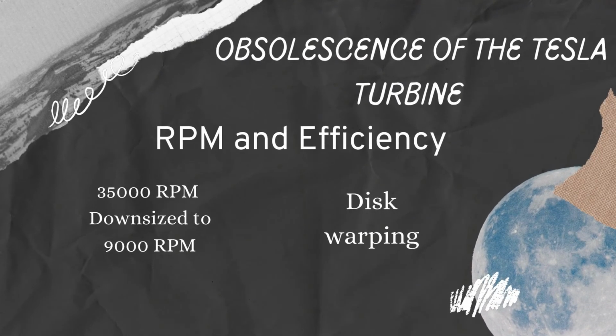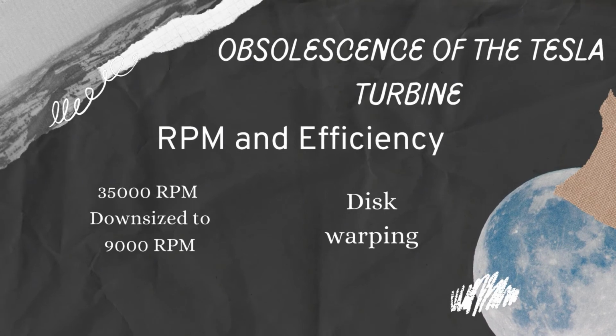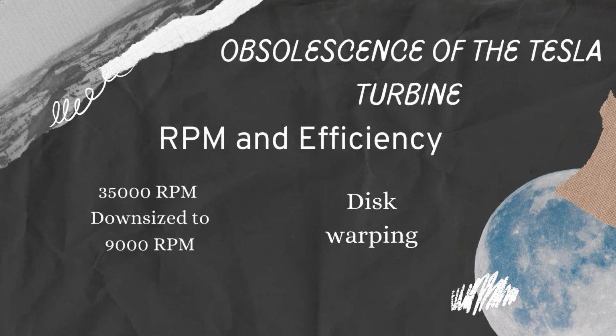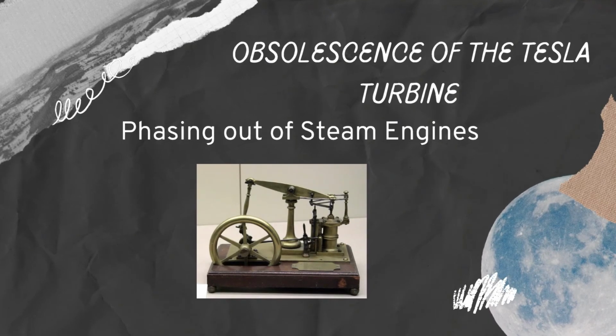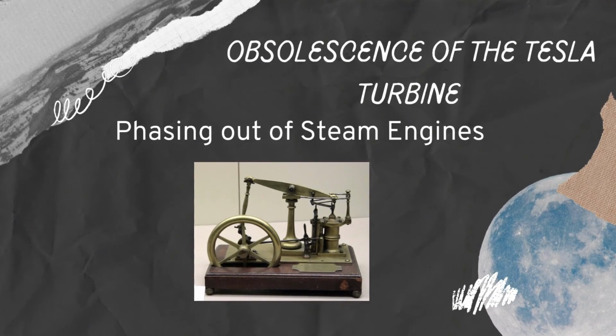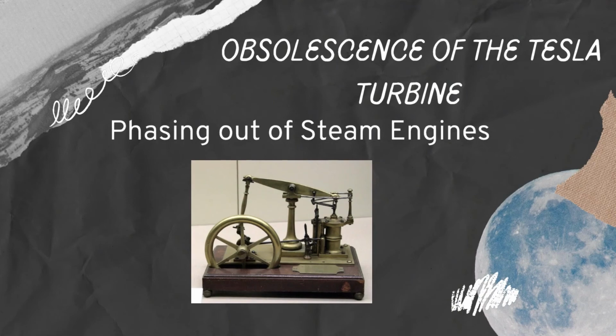So, Tesla had to reduce the RPM to around 9000 RPM, and change the diameter of the discs and the spacing between them. This affected the efficiency, which came down drastically to around 40%. Also, Tesla planned to use steam as the fluid in the machine, but steam engines and similar products were already being phased out at the time during the 1920s, and internal combustion engines were being developed.